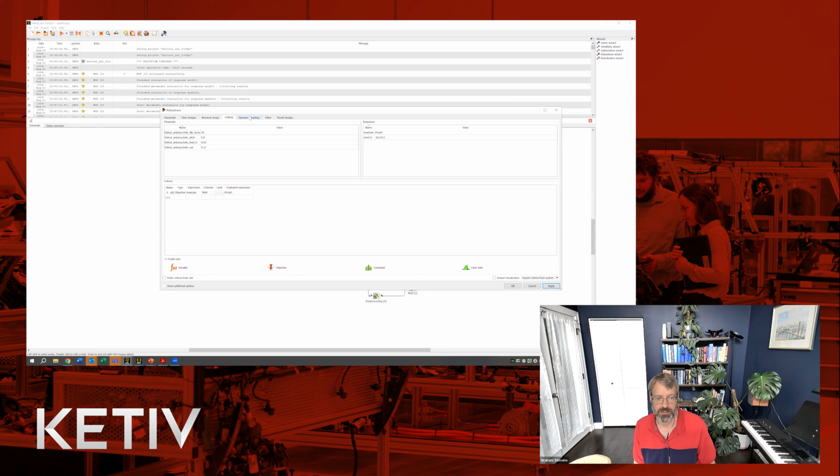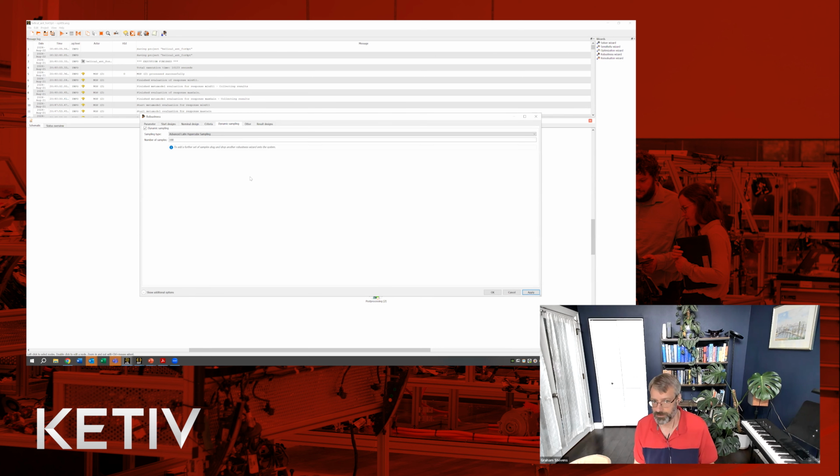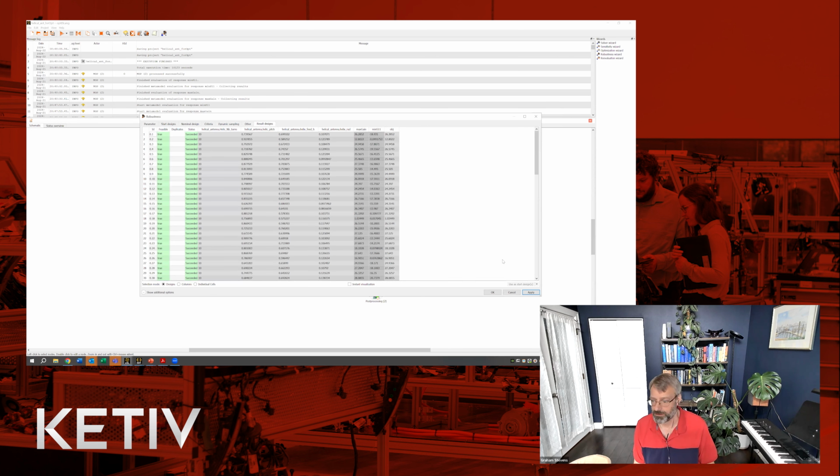This allows us to set these distributions, and then the nominal design that we're starting from, again, criteria that we try to maximize our gain. And then we set our dynamic sampling here, and this can be a plain Monte Carlo, Latin hypercube, advanced Latin hypercube, etc. In general, Optislang is trying to reduce the total number of runs, and so you generally want to go with the defaults here, and it tends to shift you away from just plain Monte Carlo, which is just at random, and try and get some more logic and reduce the total number of samples needed to get results. And then we get our result designs here.